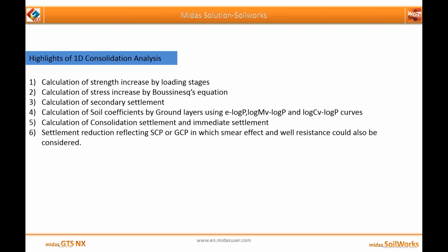So if we highlight the main features of 1D consolidation, we can say that it helps in calculation of strength increase by loading stages. Secondly, calculation of stress increase by the Boussinesq's equation, calculation of secondary settlement, calculation of soil coefficient by ground layers using the e-log P, mv-log P and cv-log P curves. Okay, then calculation of consolidation settlement and immediate settlement, and the settlement reduction reflecting SCP or GCP, in which the smear effect and the well resistance can also be considered.